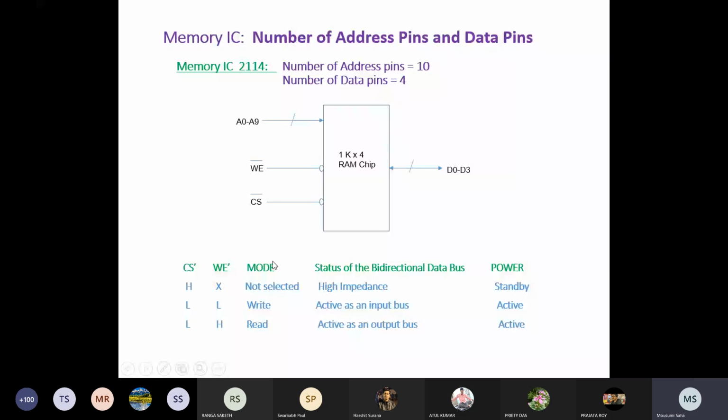So this is the 2114 IC, or 2114 memory chip, where you have 10 address pins, 4 data pins, and some control signals, W and CS bar. Others you have, no need to consider for this design, because in our computer architecture subject we never consider the exact pins and exact control signals. If we consider everything, it will be more complicated to design.